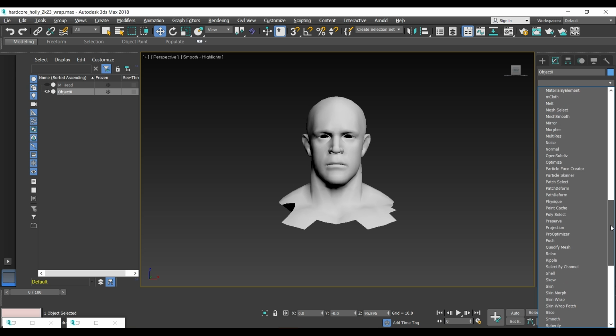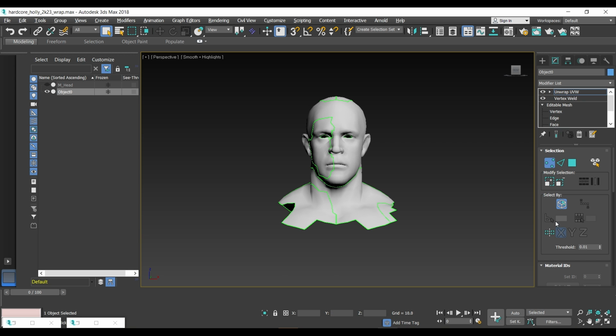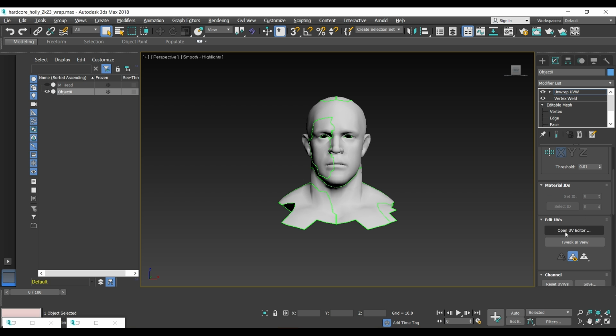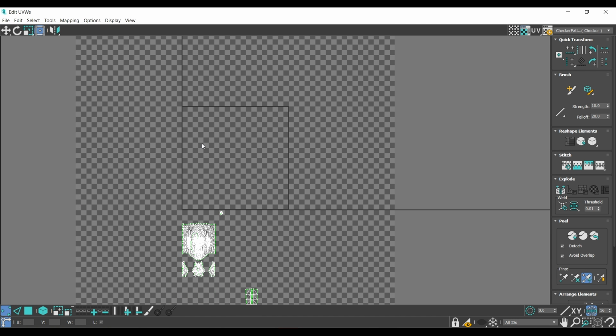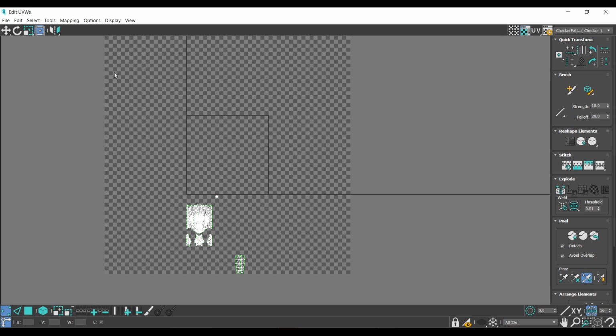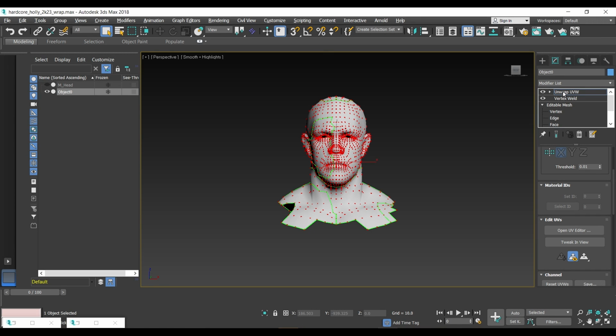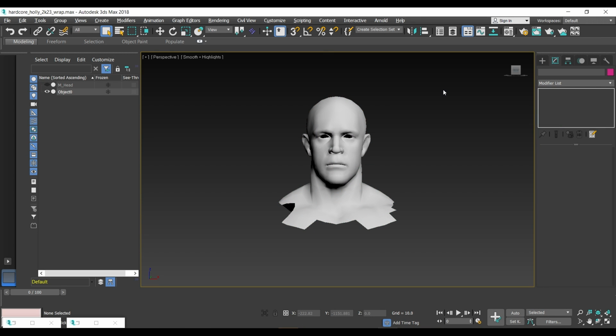I'm going to open the UV editor, and we need to make sure that this model is within the square block here. So we select everything and click the move selected object. Where it says V, you hit 1 and press enter. This will bring this within that block. And we hit save.